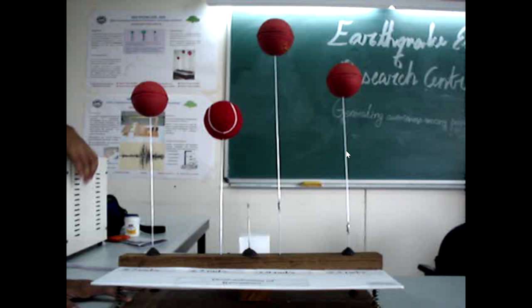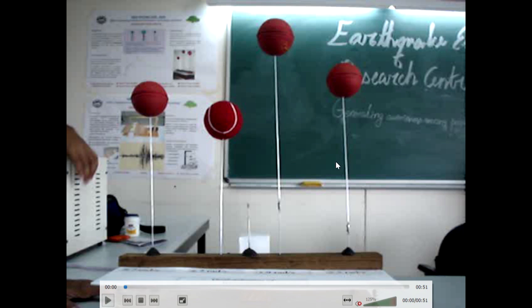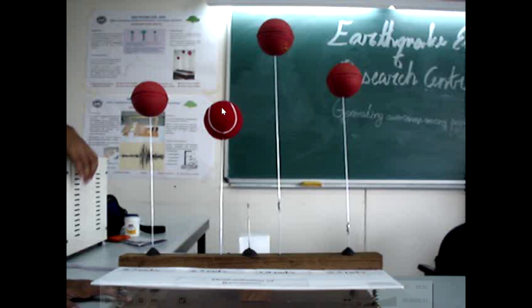Tall buildings will have more natural period, short buildings will have less natural period. The second one has slightly lesser natural period, and the first structure on the left and the second structure are matched such that their period is the same. That means the lengths of the buildings are slightly different, but mass is adjusted such that both natural periods are the same. Now, if we excite all these buildings at some frequency, what is going to happen?